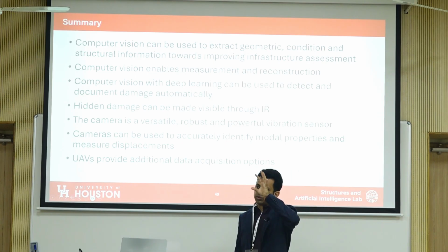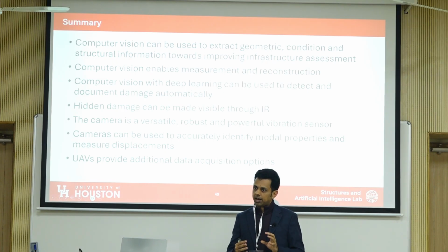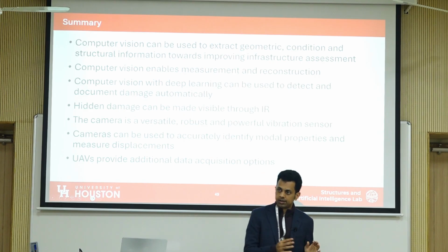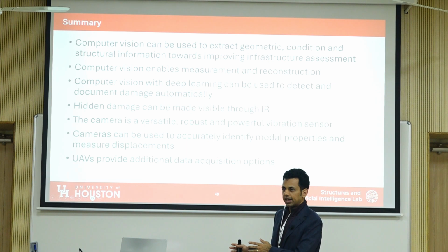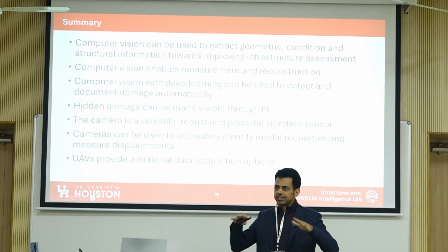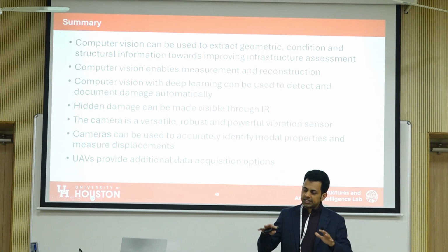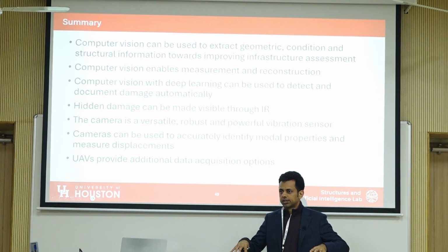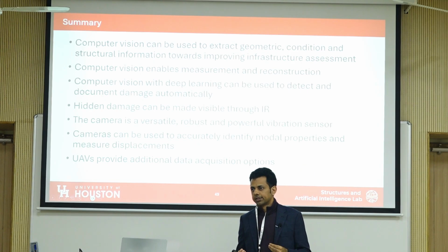And as the sun moves, the shadows will move, or maybe there's cloud cover that comes and goes. Because of those shadows, a part of the structure that looked a certain way at 9 a.m. is going to look different at 11 a.m. and different again at 1 p.m. So ideally, for photogrammetry, you want a cloudy sky but no rain, so that your drone doesn't get affected. A cloudy sky has diffuse shadows, so it's sort of uniform lighting, and that's ideal for photogrammetry.